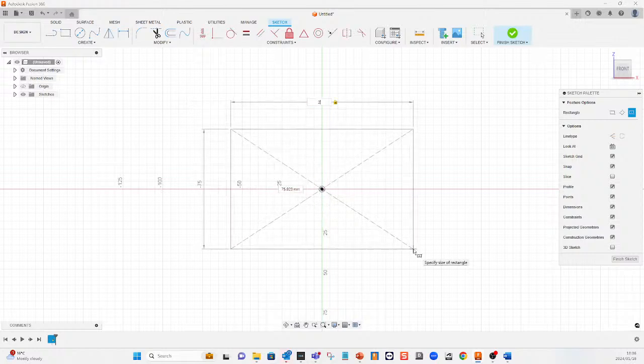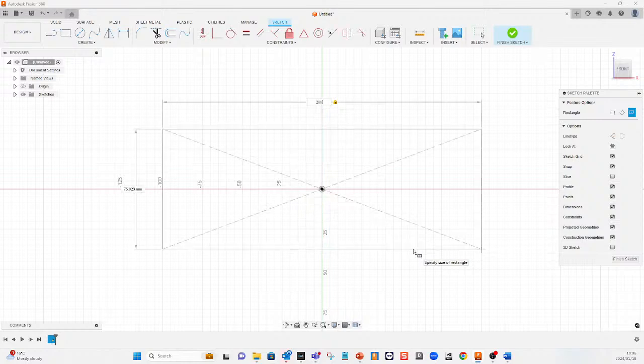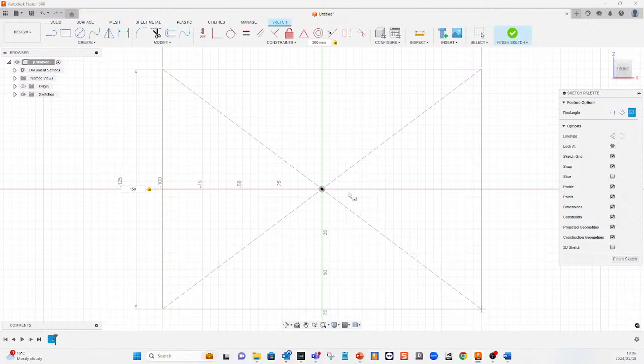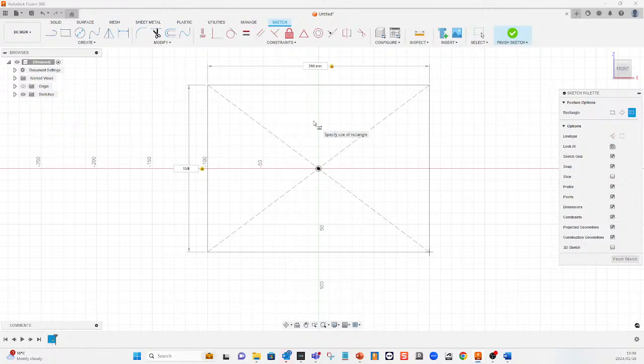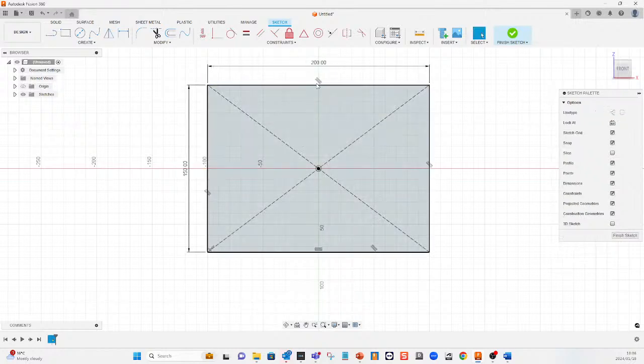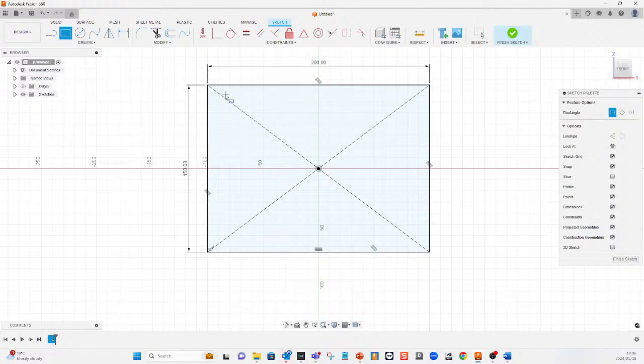Let's say I want it to be 200mm. Then I press tab to change to the bottom tab. As you can see now, I can change the dimension over there. So to switch between the 2 tabs, just press tab on your keyboard. Now I'm going to press enter. Now I've got a nicely constrained 200 by 150 block. I'm just going to create a normal block, for instance.